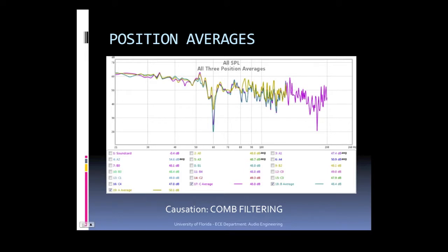By varying the distance of the placement of a subwoofer or any loudspeaker from a surface with a high reflection coefficient, you can adjust the amount of reverberation and, in effect, the amount of gain achieved through comb filtering. For the highest possible gain from the lowest input signal, placing a subwoofer or speaker against a corner would be ideal because it provides 3 surfaces for the original sound source to reverberate against: the floor and the 2 intersecting walls. In contrast, if slight or no additional gain is required, then placing the loudspeaker more towards the center of the room away from the walls would be the most ideal.